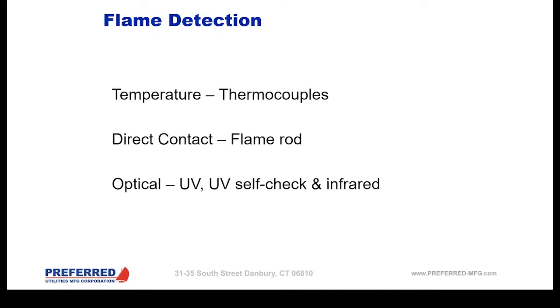Optical, definitely the most popular, no question, particularly on larger burners, commercial and industrial. And these will come in different flavors, UV, which is ultraviolet, and then ultraviolet self-check, which we will talk about a little bit further, and infrared.